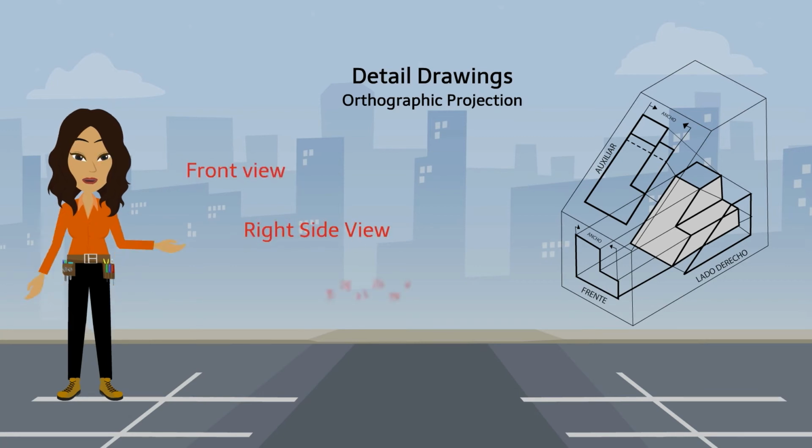Keep in mind that the views must maintain their correct orientation. These two-dimensional views are used because they make it easy to add dimensions to the drawings. Take care and only use the number of dimensions necessary. Do not duplicate dimensions. With the orthographic projection, you also find a half-scale isometric drawing that completes the plan. For most objects that we draw orthographically, we only require the three basic views, called standard views: front view, right side view, top view.